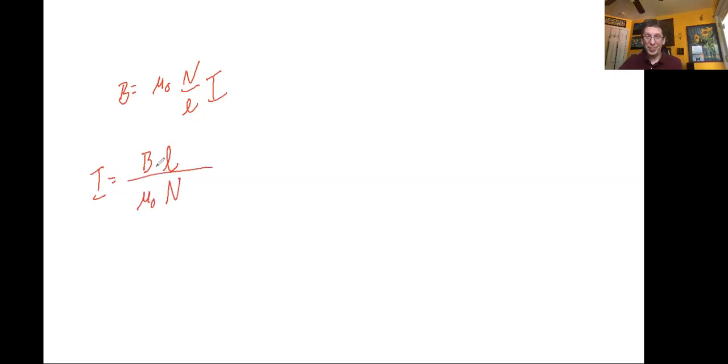Notice there's no pi term here to cancel things out for you. So what I recommend doing there is dividing by pi and then dividing by 4 times 10 to the negative 7. But let's write these numbers in. So the magnetic field is designed to be 0.385 millitesla.